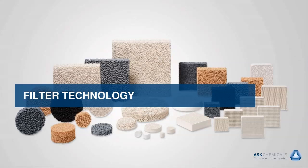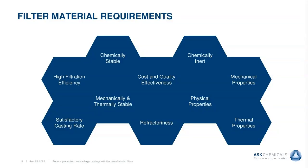Let us now switch over to some basics of the technology of ceramic foam filters. Because of the typical application, that means molten metal with high temperatures and pressure, there are some very important requirements which the filter material must fulfill. You can see them on this slide. You need a chemically stable material, mostly chemically inert. It must of course be mechanically and thermally stable, and it must also have a high refractoriness. Good thermal properties are also very important.